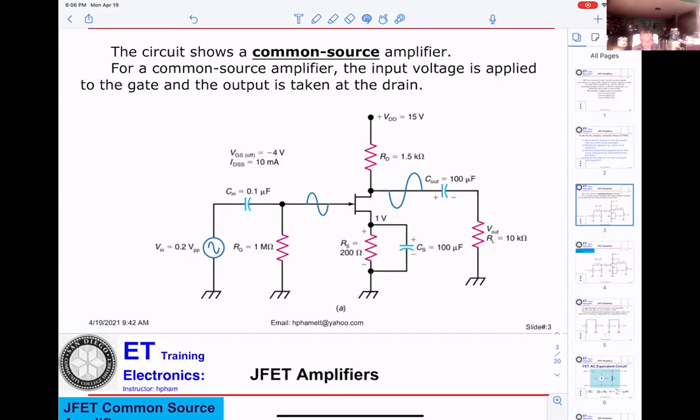I'm thinking, if you're looking at the gate bias, fixed bias, then you still see a resistor here. Oh yeah, of course. Basically, from my understanding, that resistor connects to the ground. For this circuitry, we don't have any DC, and that's just an input impedance for this amplifier.